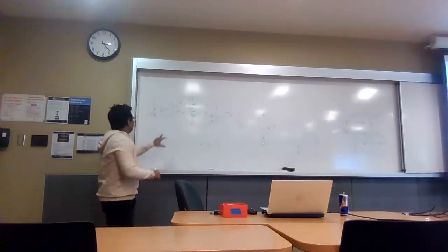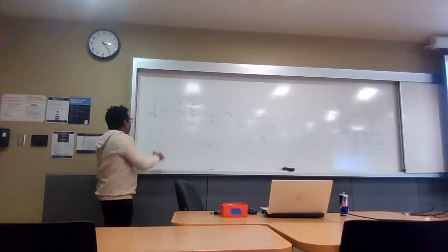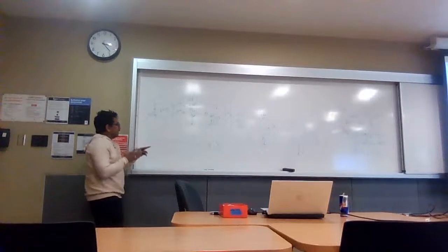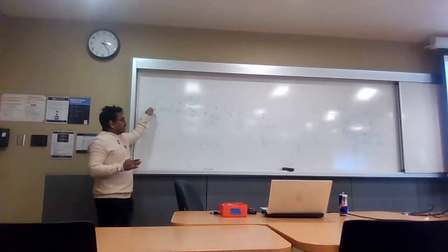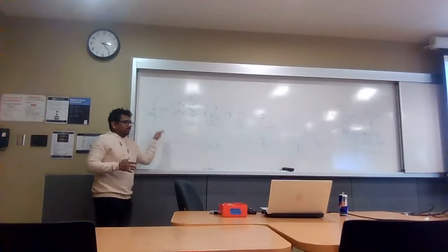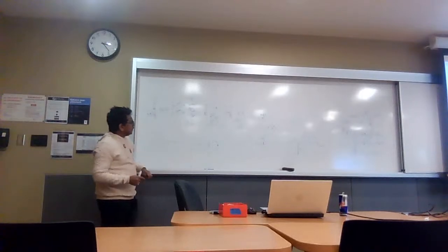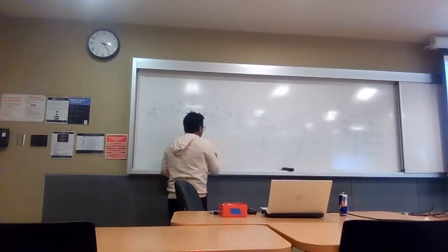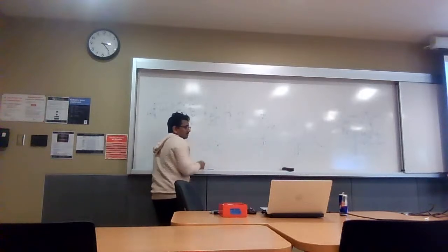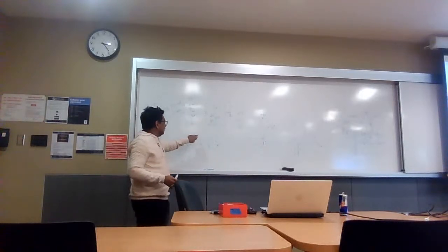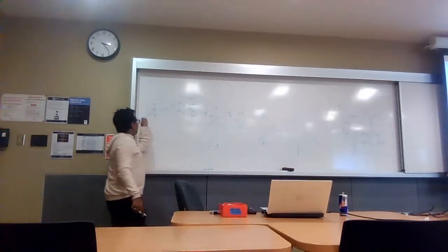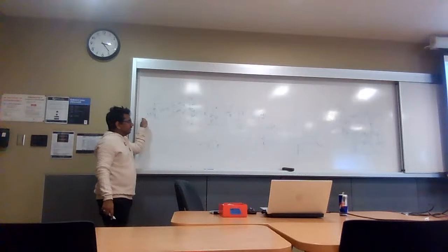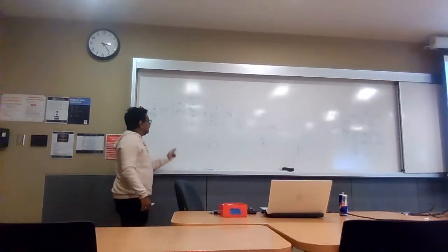It is the job of this PFD to always compare whether this signal is 100 megahertz or not. If it is increased from 100 megahertz, it does something. If it is reduced from 100 megahertz, it does something and adjusts it again. So what should this divider be? It should divide by 10, right? I have to design it to divide by 10, then it will divide by 10 and we will find 100 megahertz again here. So this is the beauty of the PLL.